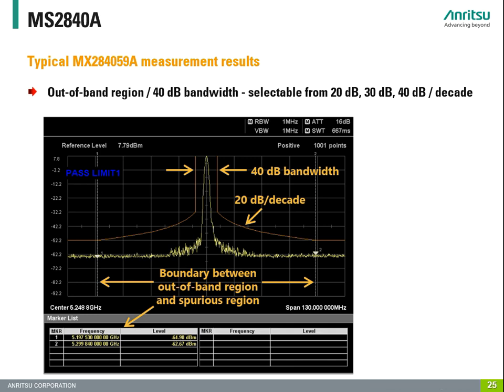It is required to measure the 40 dB out-of-band rejection. This is the measurement according to the just mentioned ITU standard. The current plot displays the behavior of a solid-state power amplifier. The two markers cover a 100 MHz span, the so-called spurious domain.